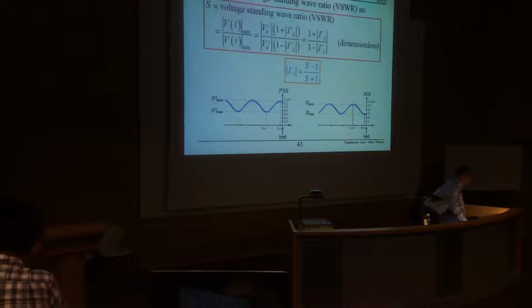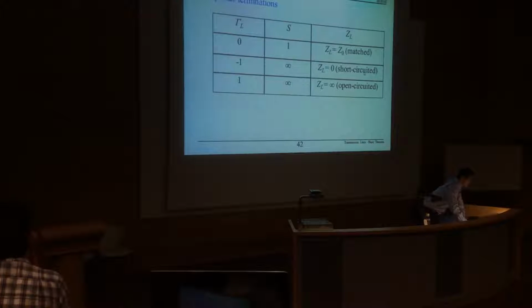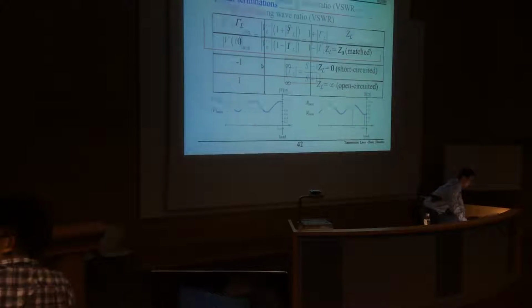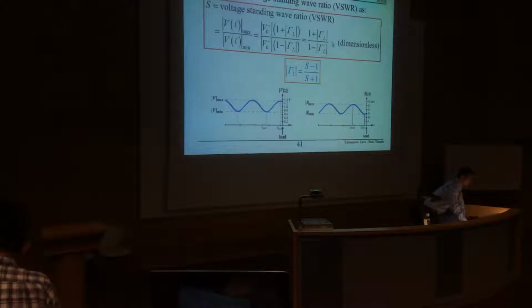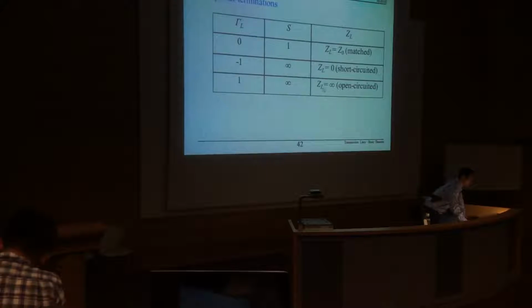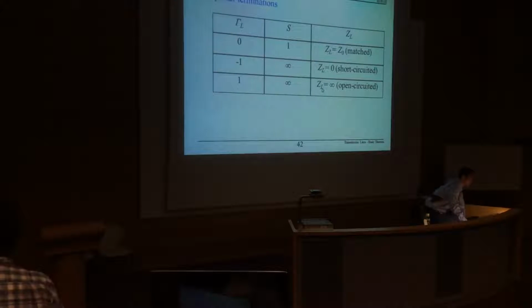For another case, if it's a short circuit, the reflection coefficient is -1, then the standing wave ratio is infinity.